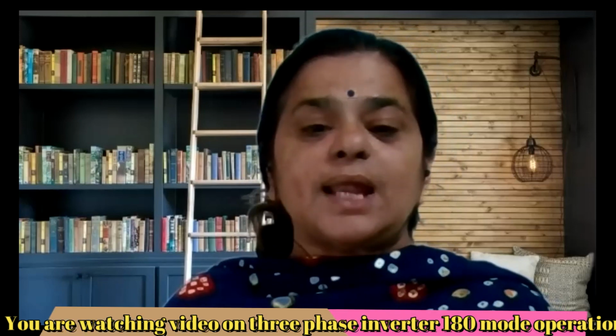Dear friends, I hope all of you are aware of the inverter, but for those who are not, it's a kind of power electronics converter by which you can convert a DC supply into an AC supply. As you know, the AC supply is available in two forms. So accordingly, inverters are of two types: the single phase inverter and the three phase inverter. A single phase inverter is a type of converter by which a DC supply can be converted into a single phase AC. It means the input will be DC and the output will be single phase AC.